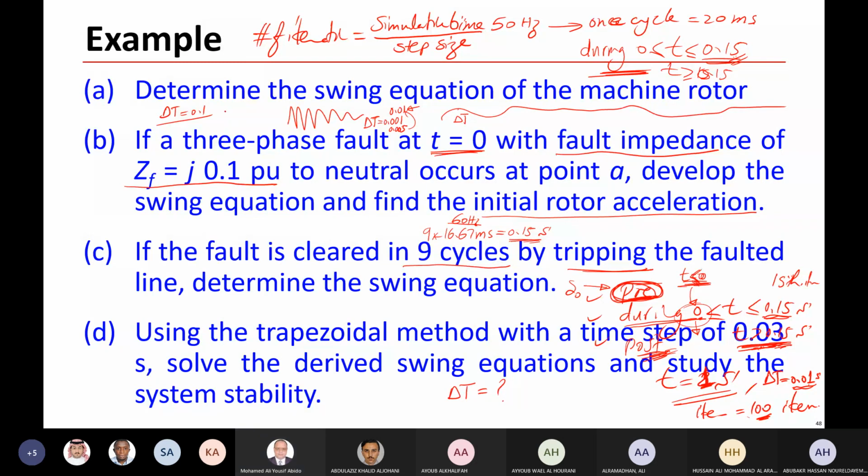Delta is increasing monotonously. In this case, you don't know whether the system is really unstable, or your step size is too big.